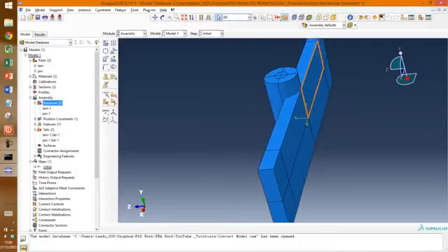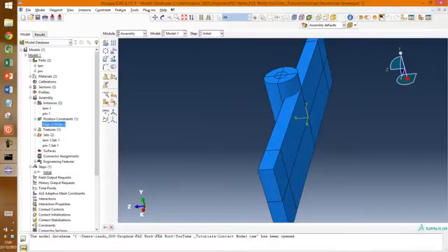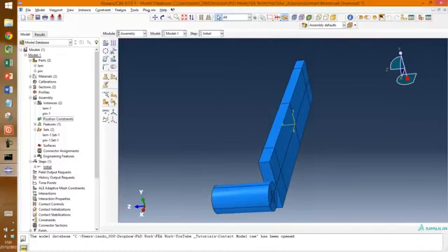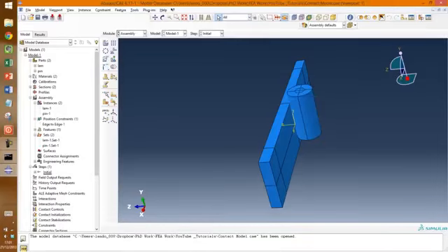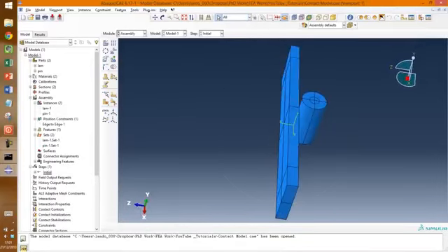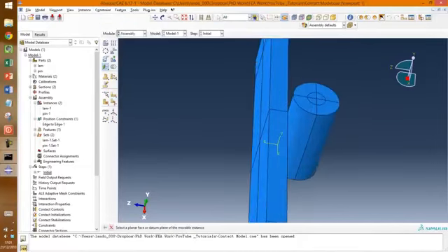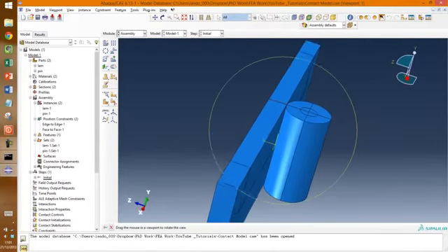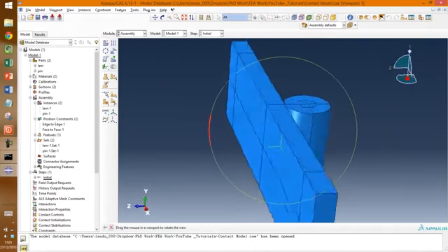Okay. I'm actually going to delete that edge because it's flipped to the wrong side of it. Okay, so try that again. Constraint, edge to edge, that, and try the default. Okay, that's fine. And now use face to face. So I'll just select that face and that. Make sure they're pointed the right direction. Set the distance part at 0. Okay, so now it's just positioned correctly.